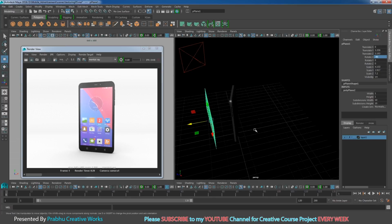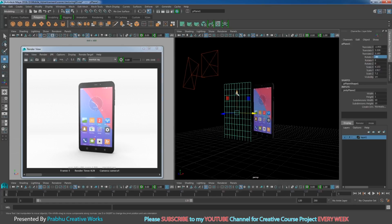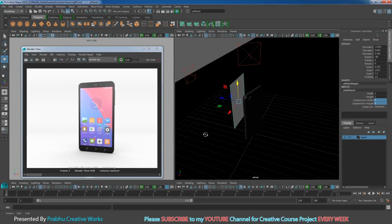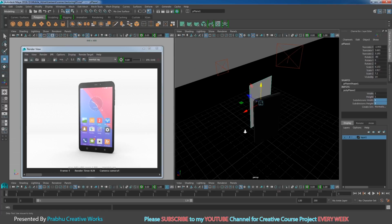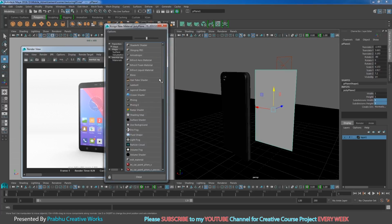You want to keep it exactly straight, but you want to cover half of the mobile like this. Give divisions to 1, subdivision width and height to 1. Here you need to apply a surface shader for this object. Right click and choose assign new material and choose surface shader.